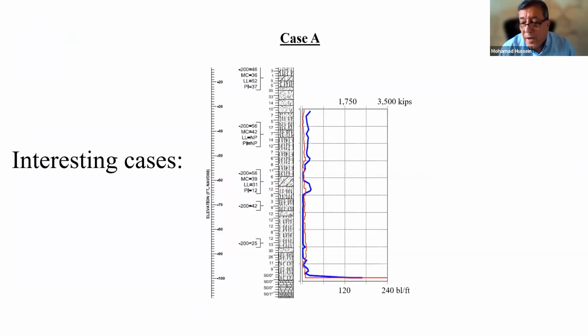And this is a case where you see a soil boring in there, and clearly the piles will drive down to about elevation minus 100, and they will hit refusal. That's what happened. You see the blow count going up and hitting refusal, the pile capacity increasing, and then hits refusal at exactly what's expected. So that would be a case where really a test pile program would not be very effective or useful because, well, the length of the pile is pretty much known here. And the installation of the piles can be instrumented in order to control stresses and avoid damage.